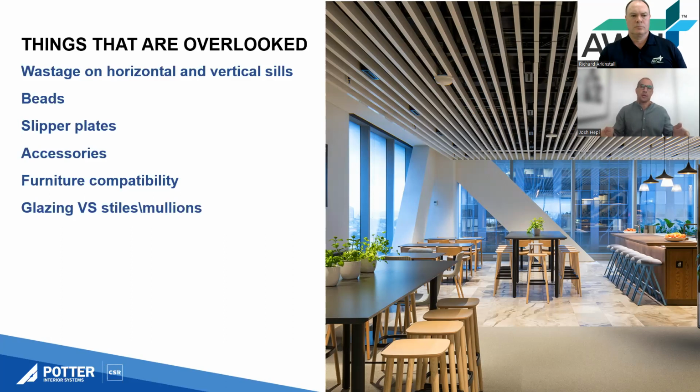And so as I mentioned as an example before, if you've got 4 meters of partitioning, that's 1.6 meters of probably wastage. You might be able to use that somewhere else if you've got a small door or window, but it might be wastage, and you don't want to then reuse that 1.6 meters and join another piece to it to form a window with a join in the head. You ideally want full lengths where possible.